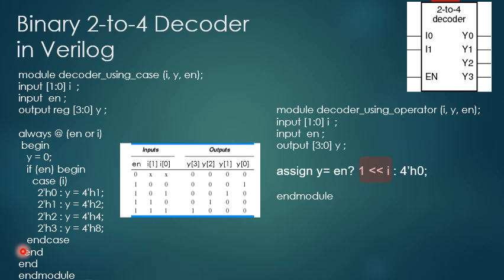Actually, in this case, you don't need to have this pair of begin and end, I mean not necessary to have this pair of begin end, because under the if there is only one statement. So having the begin end is nothing wrong, okay, but you can also remove it since it is only one statement, and you don't need to enclose the statement with begin end. Okay, so this is one way, and then the second coding shows how it is described using the